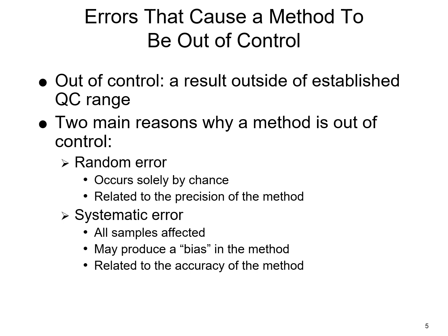Maybe the room temperature, you're noticing that at certain times of the day you're getting some random results, and maybe at a certain time of the day the room's getting too hot, and then it's causing everything on that machine to start shifting a little bit, and so you're starting to see those shifts and trends happen. And so that alerts you that maybe something else is going on that you need to investigate.